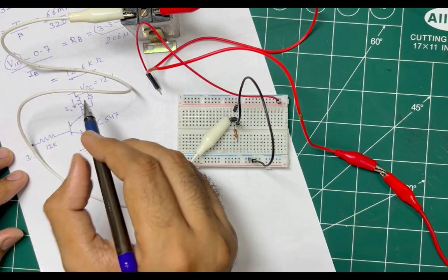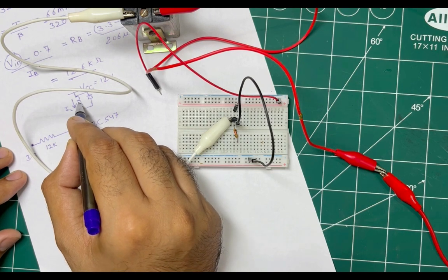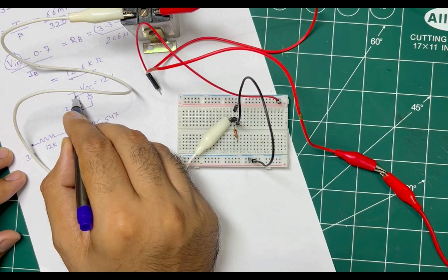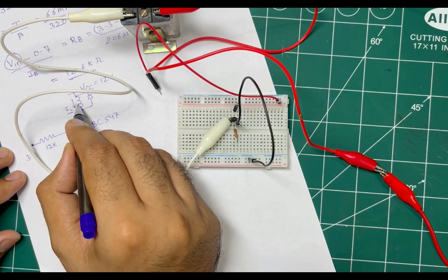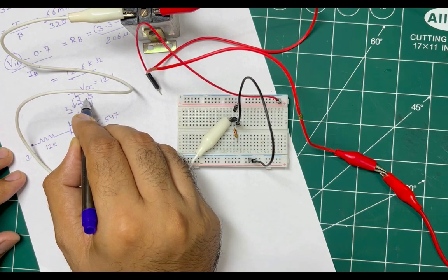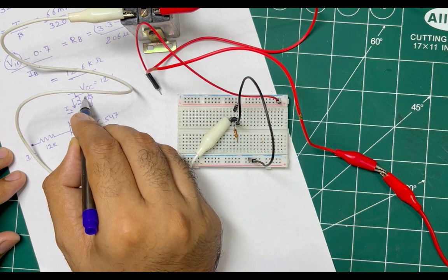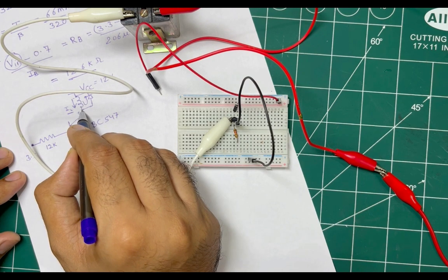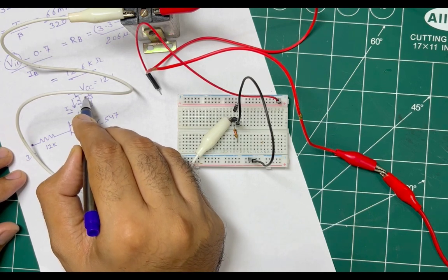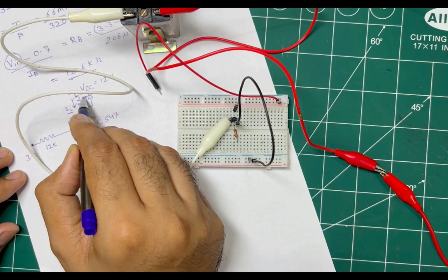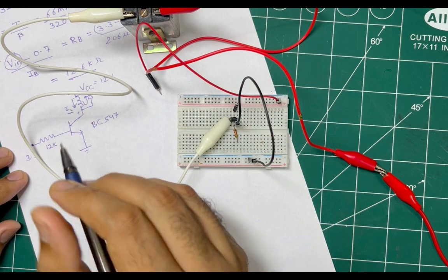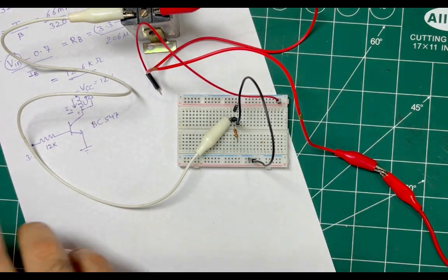To prevent that from happening, we insert a freewheeling diode. As soon as the load current tries to stop, the voltage induced in the relay tries to keep that current flowing via this freewheeling diode. The diode gets forward biased immediately when the magnetic field starts to collapse, and the current can then enter into a loop and keep on flowing until it dies due to the losses in the circuit. And that is why this diode is called a freewheeling diode.